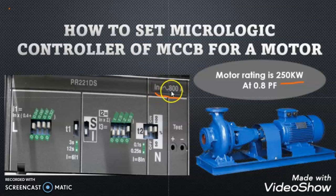This IN equal to 800 ampere is the nominal current rating of the breaker. But with the help of this L setting, we can change the nominal current rating of the breaker, which is called the rated current rating of the breaker.